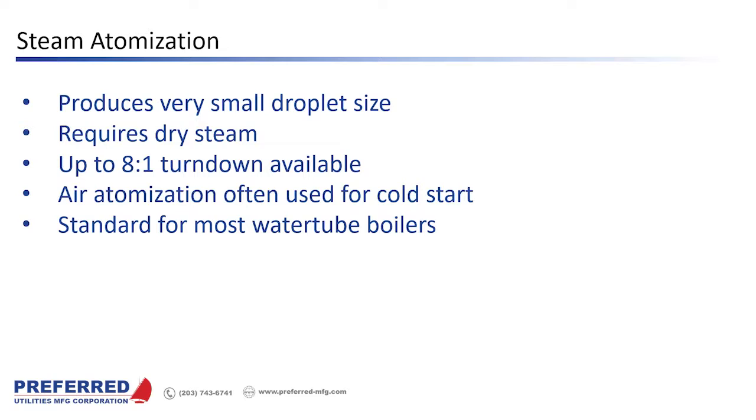And it'll usually come back on when that switch makes again. But you've got to go through the purge cycle on the burner and you've got to light off again. So shutting down the boiler, letting it draft cold air, and then purging it and lighting it back off again are kind of hard on the burner and the boiler. So we would prefer not to do that if we can help it.